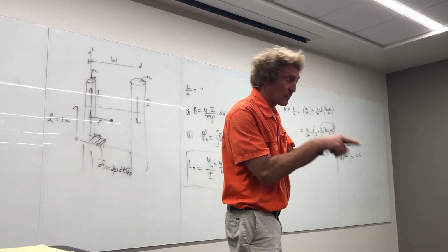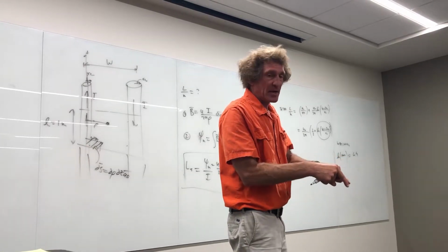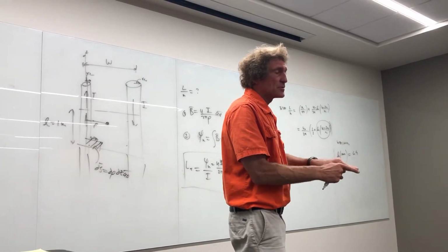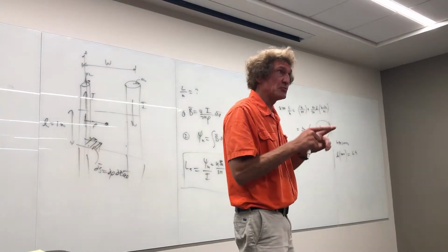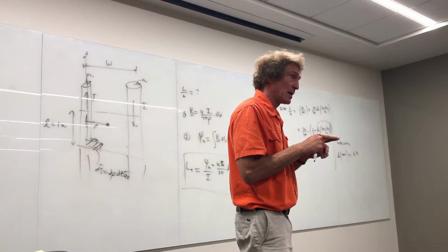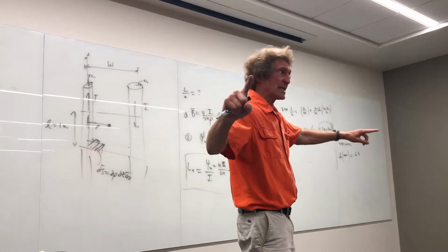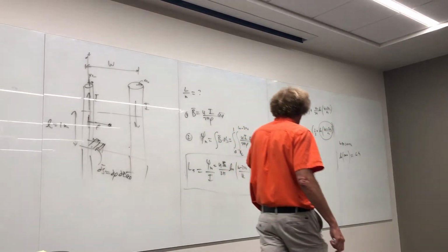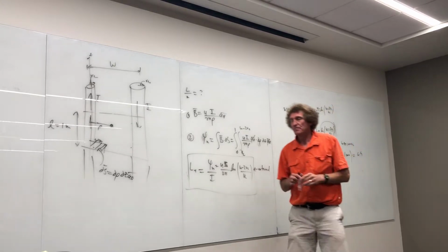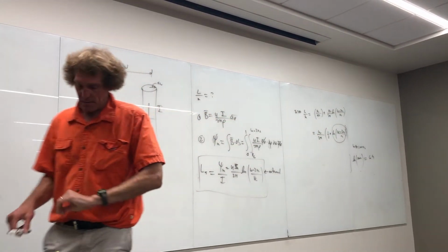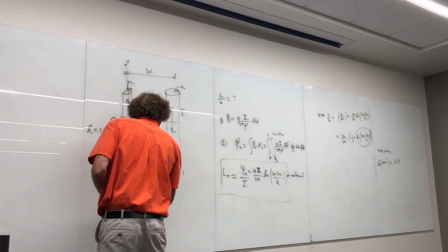Then the internal inductance will dominate. And that's the thing. If the wires are literally next to each other and wrapped tightly in order to prevent EMI and EMC problems, then in that case, the internal inductance per meter takes precedence, which is 2 times mu over 8 pi per meter. And if they're separated by a great distance, the external inductance, or this term right here, takes precedence. That's important.